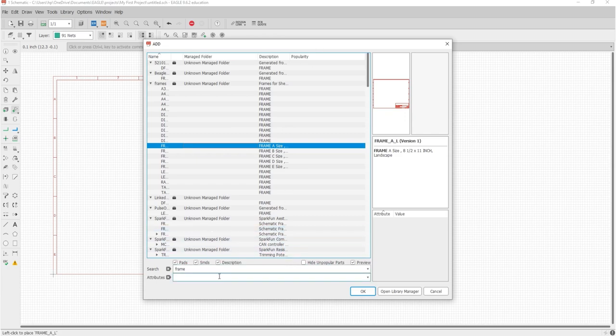In the circuit, we will use PTH or plated through hole components. To ease us when we're searching the component, we can uncheck the SMD option here. So, the result that will appear is only the PTH or through-hole component.